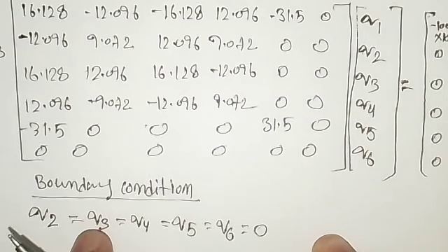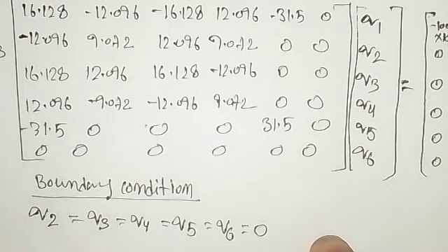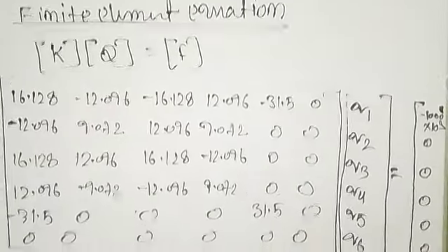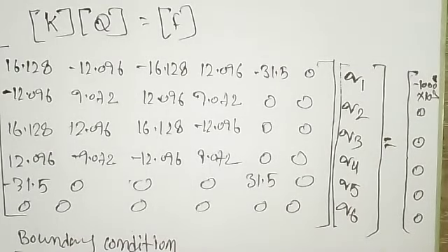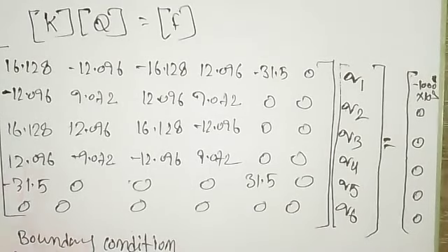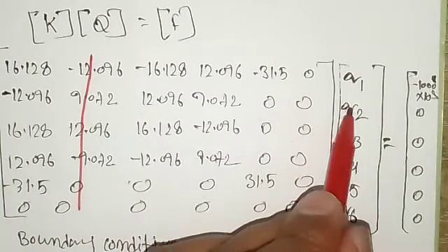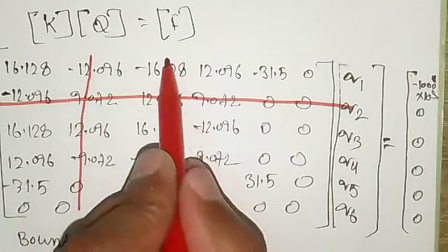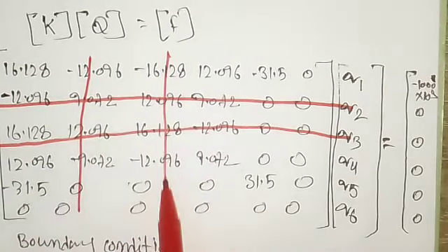So when we impose the boundary condition, it means that except the first row and first column, all the elements will be eliminated, right? So we can impose the boundary condition here only. So this is how you can eliminate that. First we are eliminating Q2, means this is the Q2, right? Second row, second column, again you have third row, third column, right?